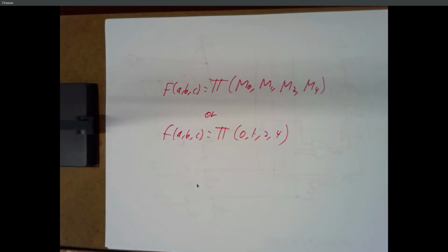One more thing I want to clarify. So on number 3, you'll also want to include the don't cares in the Kmap. The don't cares will help you get a smaller circuit usually, so you always want to consider them. Now if covering them doesn't help you, then don't cover them.